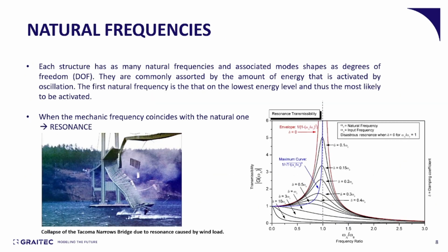Let's see now another important term that has been implemented so far in this presentation, natural frequencies. Each structure has as many natural frequencies and associated modes as the degrees of freedom of the structure. They are commonly sorted by the amount of energy that is activated by the oscillation. The first natural frequency is the one with the lowest energy level and thus the most likely to be activated.